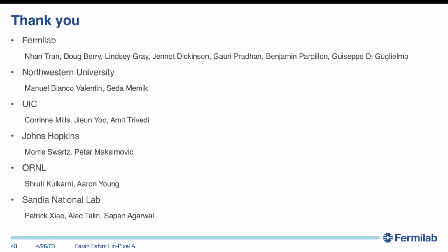we designed our methodology of going from the algorithm to accelerator for Econ, and we've very successfully tested Econ. Got very good promising results. Econ does the exact same thing with programmable weights, so you can customize it based on the detector geometries that we can see in different areas of the detector. Even in Econ, the number of bits coming in from the front end was something like 22 bits. We did some pre-processing to convert from 22 bits down to 8 bits, so that we could keep a compact neural network. And this is exactly the same thing that we are doing here.